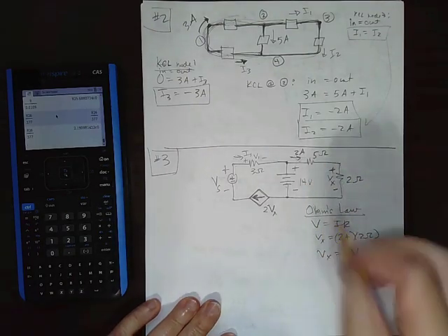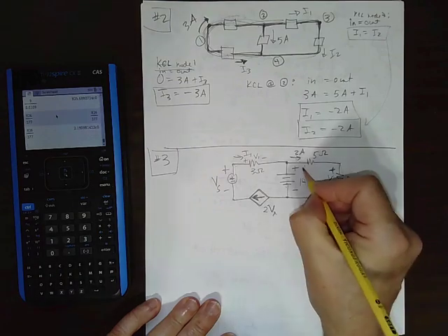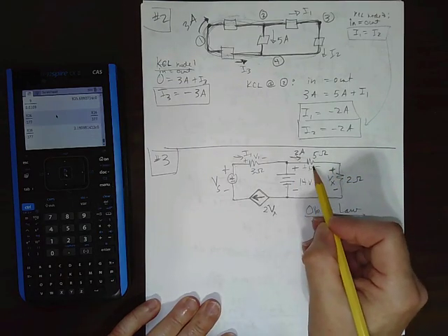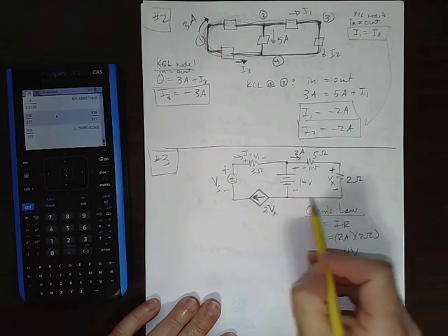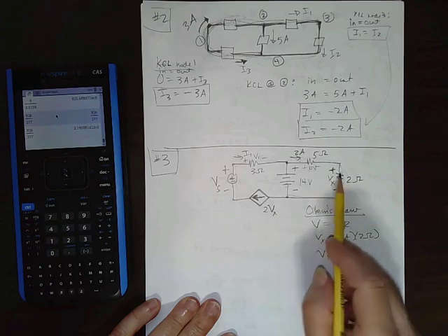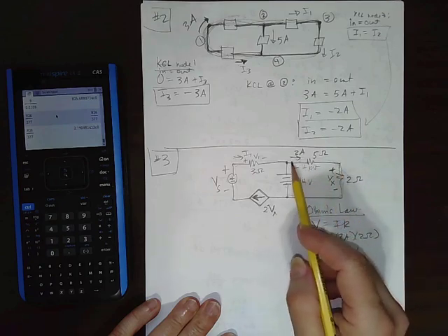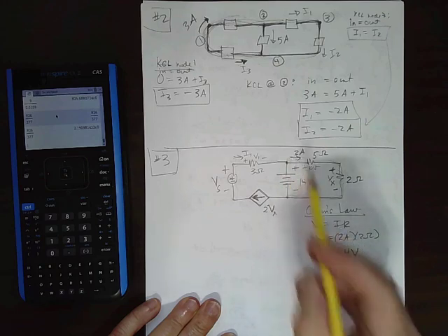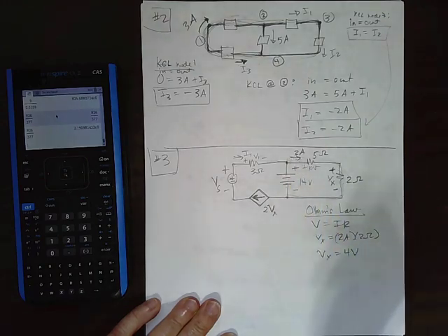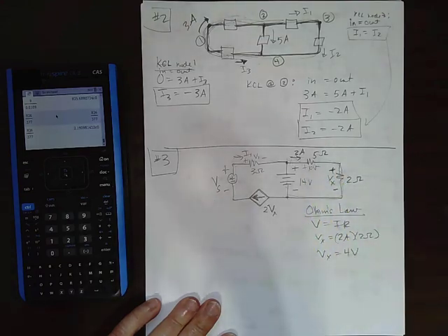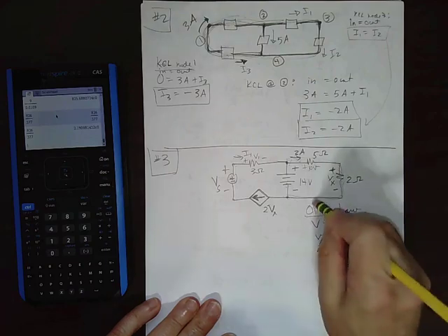All right, so we got the voltage here. We could also, if we want to get the voltage here, what does it have to be? V equals I times R. So this is going to be 10 volts. So that's good because if we go up to get to this point, we go up 4 volts, go up 10 volts. So we got to 14 volts, which has to be the same as if we went from here to here. Go up from here to here, we should go up 14 volts. So those agree, so that's good. So that's why I'm saying we could have used this source to figure out that voltage as well. But we have a little bit over-specified problem here.